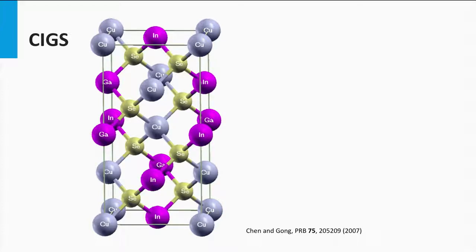A variety of CIGS alloys exist, but the best performing layers have something in common. They contain a polycrystalline alpha phase. The lattice atoms are tetrahedrally bonded. Such a lattice structure is a so-called chalcopyrite structure, as you can see in this illustration.